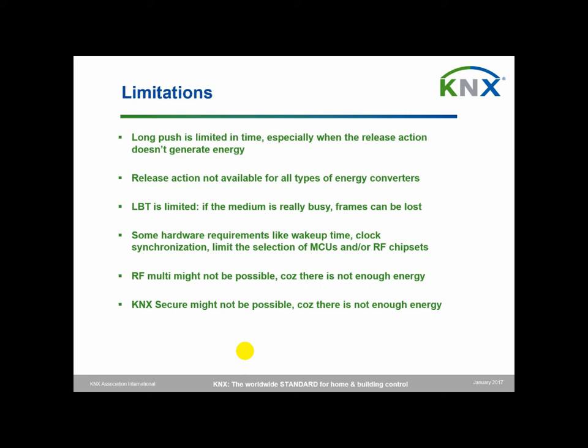Also could be critical: some hardware requirements like the wake-up time and the clock synchronization really limit the selection of microcontroller units and/or RF chipsets that can be used. So you need to be careful in your selection there because of timing aspects.